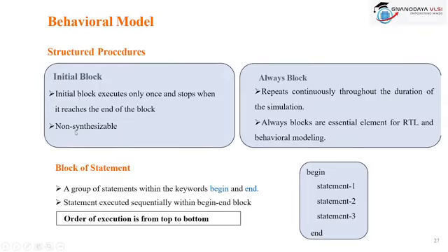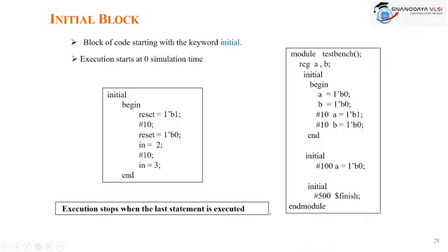So this is behavioral modeling. You need to use an initial block and an always block. The initial block will be executed only one time and is non-synthesizable. The always block will be repeated continuously, and that is a block of statements.